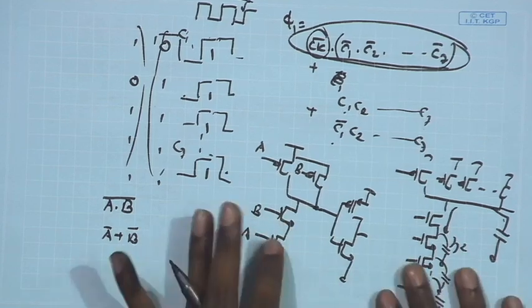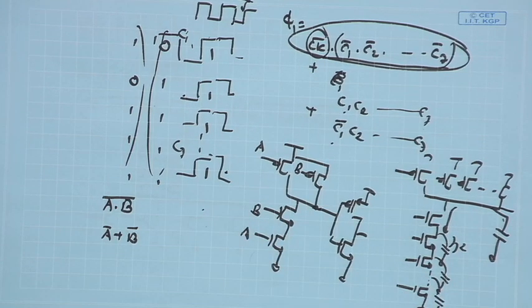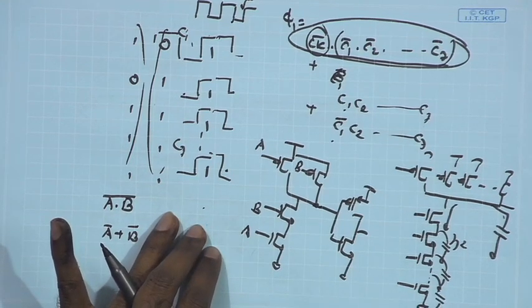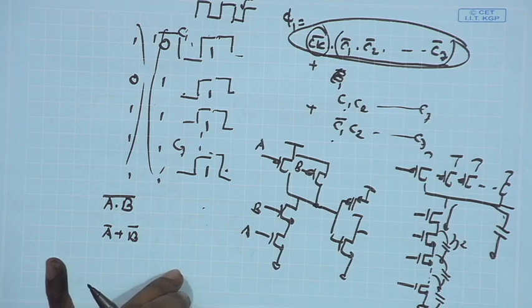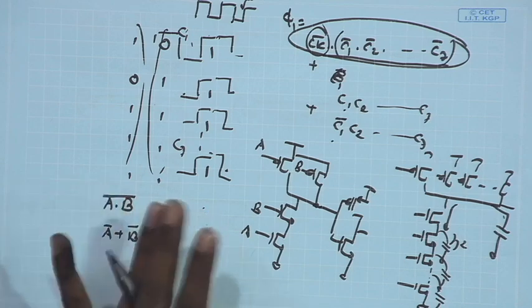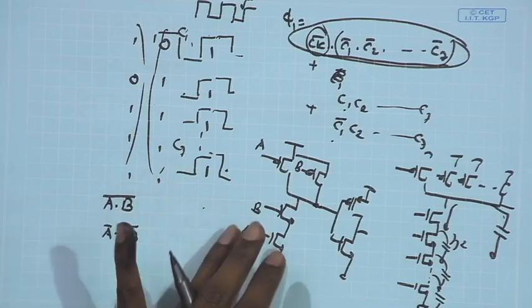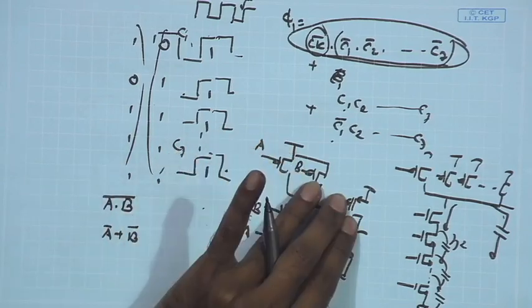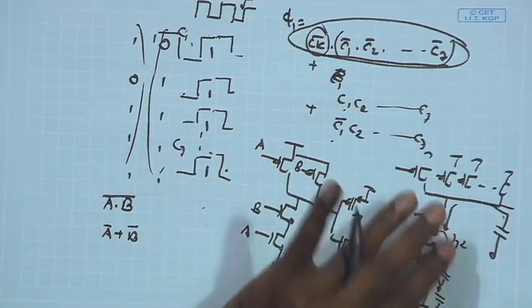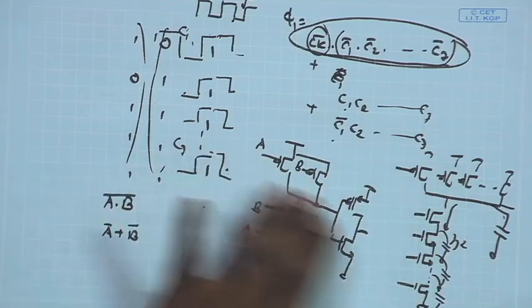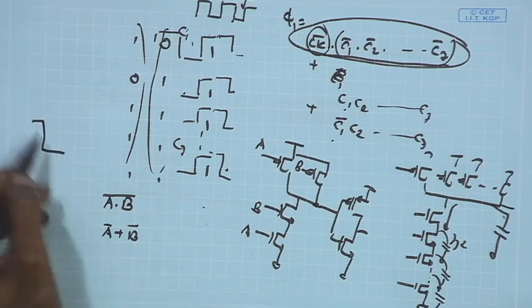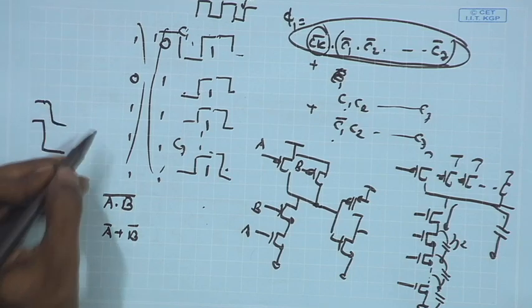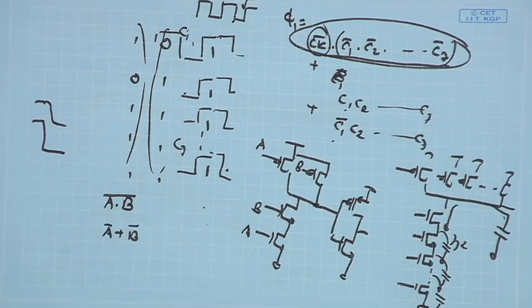Any question before we end this discussion? Sir, if the speed of PMOS is slower, then will the output synchronize? Synchronize means with respect to the clock edge, you will have a little bit more delay if you are applying the input to a PMOS or to a gate where you have more PMOS stacked. The delay will be slightly longer, so as compared to the clock edge, the delay may be slightly more. That is the only thing.